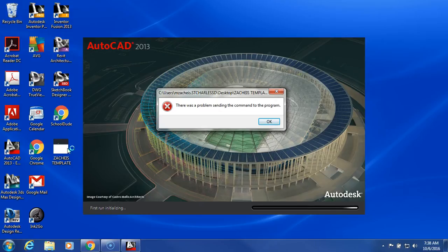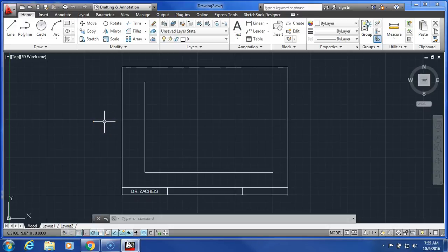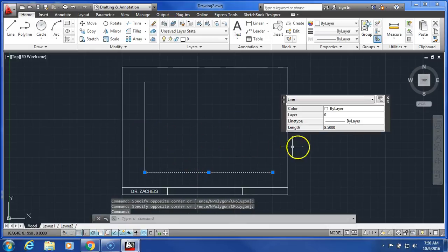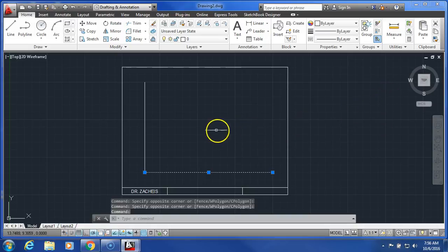that's what we're going to actually do. We're going to do a multi-view of that. We'll do a top, side, and front view of that drawing. What you want to do in the drawing here, make sure on the layers, right now, I believe these could possibly still be set on the 0 layer. What we want to do is make sure that they're construction layers.